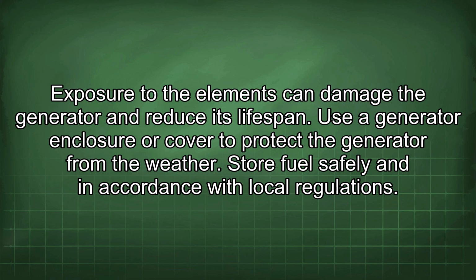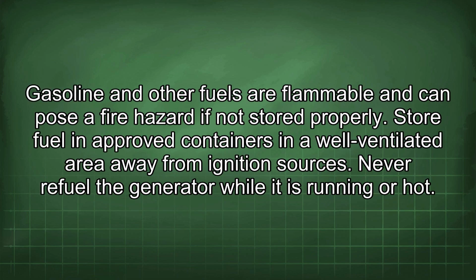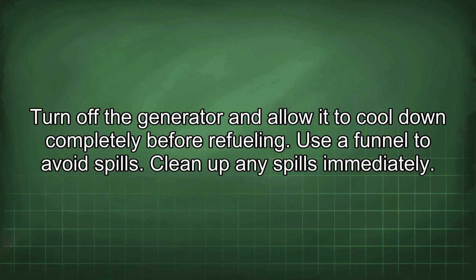Store fuel safely and in accordance with local regulations. Gasoline and other fuels are flammable and can pose a fire hazard if not stored properly. Store fuel in approved containers in a well-ventilated area away from ignition sources. Never refuel the generator while it is running or hot. Turn off the generator and allow it to cool down completely before refueling. Use a funnel to avoid spills. Clean up any spills immediately.